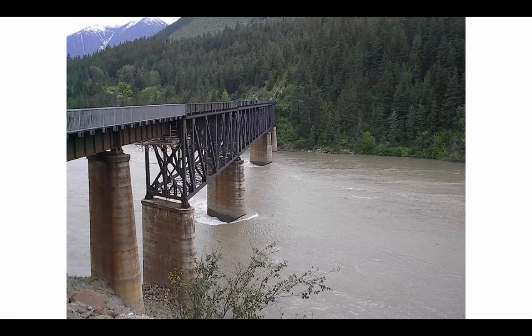All right, here is a picture of a bridge going over a river, and it looks like this is probably out west somewhere, just based on the mountains and the trees. But the interesting thing is these piers in the river that help support the bridge are reducing the effective width of the channel. You've got a certain amount of water, a flow, Q, going through this river, but when you put the piers into the channel, at this location the river isn't as wide because the water can't flow through the concrete, it has to flow around it.